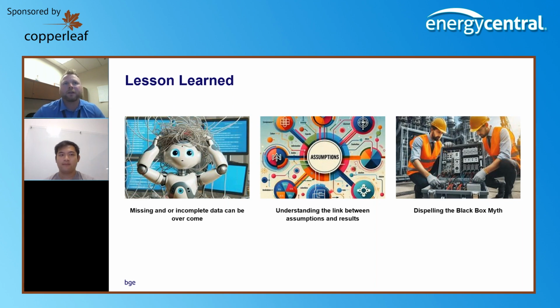Other things around, all right, we go through here and say which assets, if they were to fail, would cause an outage. And it had arresters cause outages and circuit breakers cause outages. So we ran the analysis with a constraint and it said, hey, an arrester is not very expensive to replace and a circuit breaker is very expensive to replace, so you should just replace a lot of arresters.